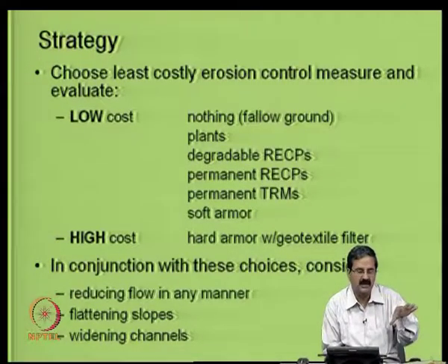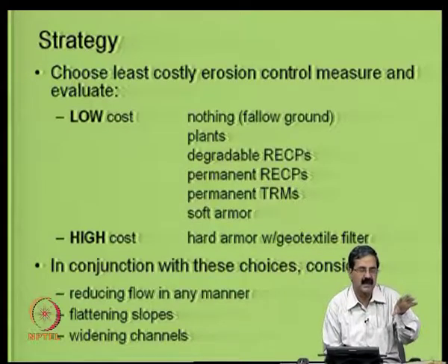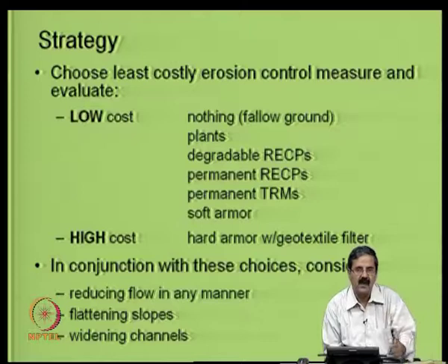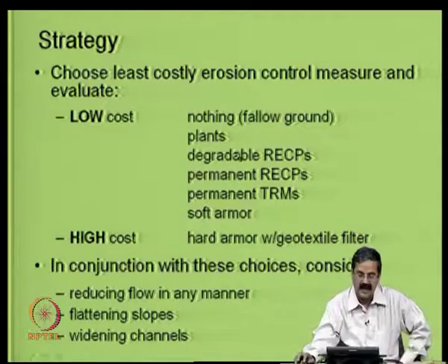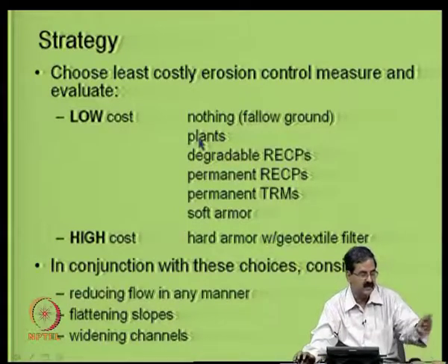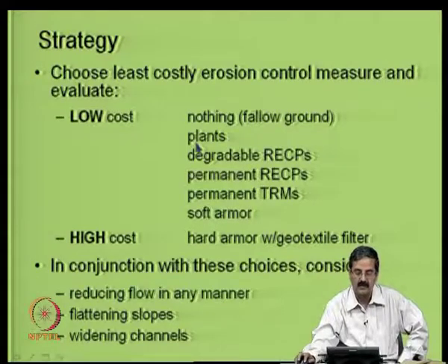You put fibers into the soil, and the soil is weak, but if you put plant fibers, the overall strength of the material increases, and strength is maintained. Okay. So one can have plants, one can have geotextile materials, or many of these materials one can use here, depending on the slope and all that.